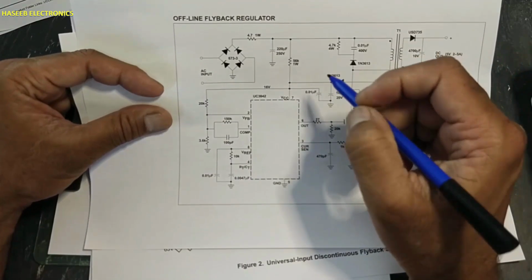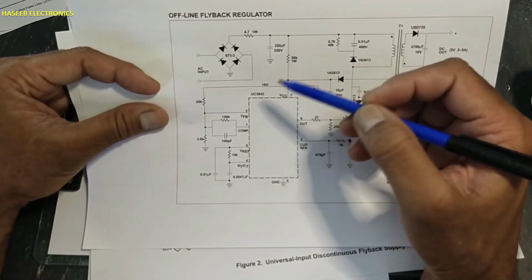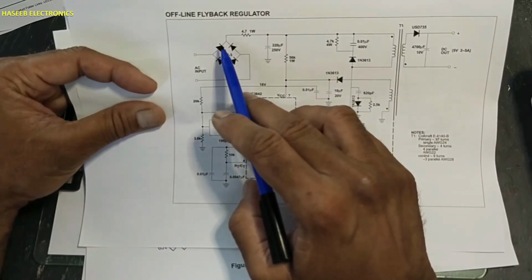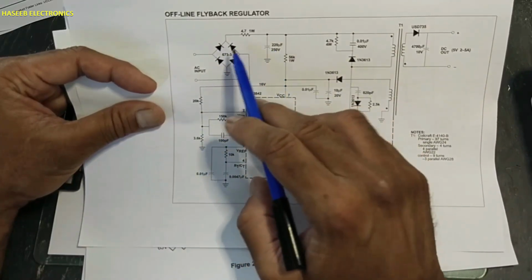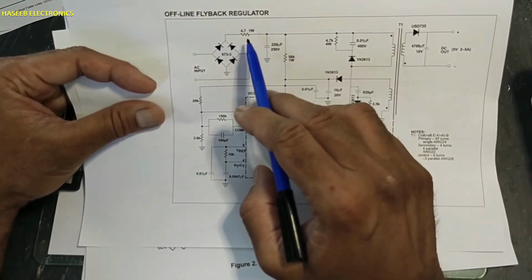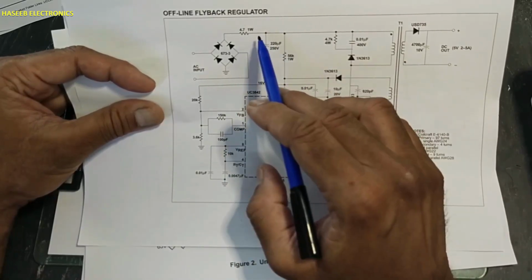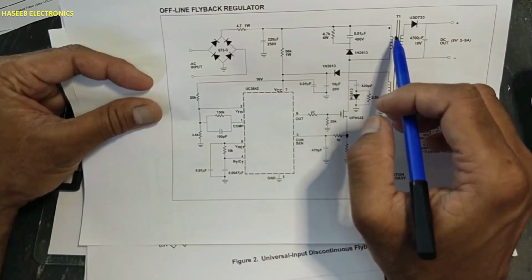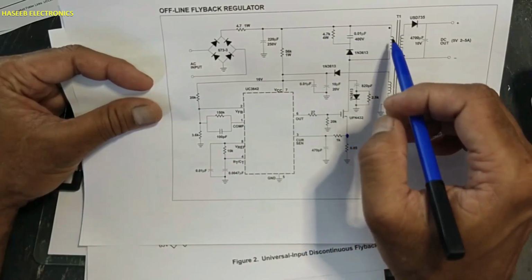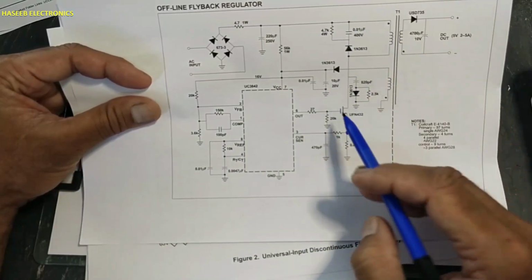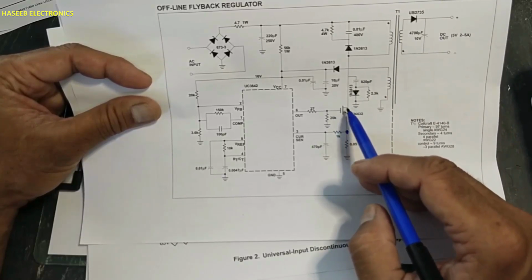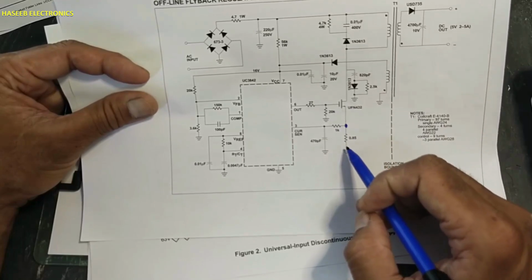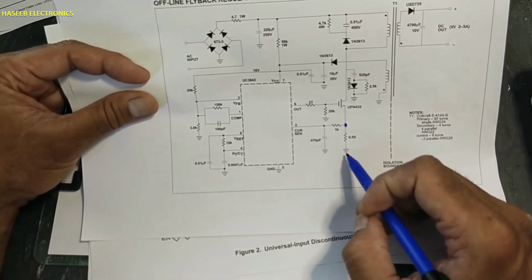Now if we see this sample circuit of the UC3842 IC, when we apply voltage to the rectifier, the voltage is rectified and the smoothing capacitor will regulate the voltage. It will remove the ripples. That DC voltage is provided to one end of this transformer winding. The second end is connected to this MOSFET drain pin. The source is connected to this resistor and this end is connected to ground.